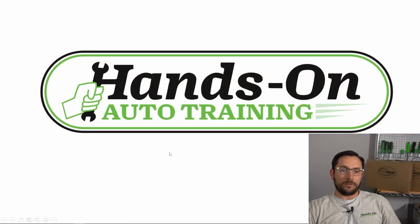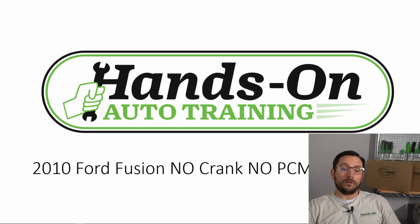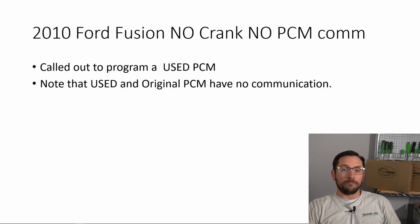So this is the case study here, 2010 Ford Fusion, no crank, no start, no communication with that PCM. I was called out to program a used computer. Okay, used ECM. The tear tag information matched all that, no problem. I want to make sure you guys understand the original computer and the used one have no communication. So right away, I kind of feel like, well, it's probably not a computer issue. I mean, it could be, but you never know.